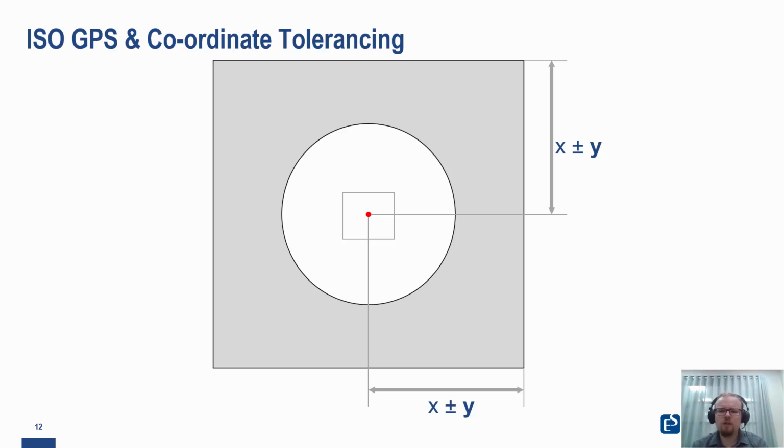But then how do we decide on the tolerance zone? We consider the furthest point from the axis as the maximum misalignment of the hole. This direction on the slide, the little grey arrow I've just added. This is perhaps ineffective though, as the variation that's permissible depends on the direction of the variation. In real life, much of the time it doesn't. We just want our hole to match up with a shaft. And of course, this doesn't just apply to holes. This is a good example of the type of benefits ISO GPS can give. So what is that benefit then?